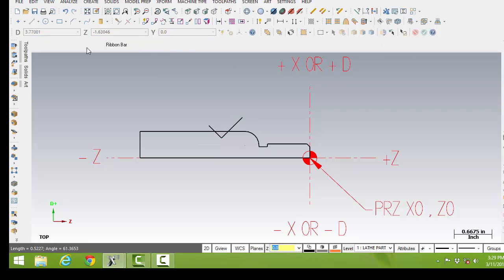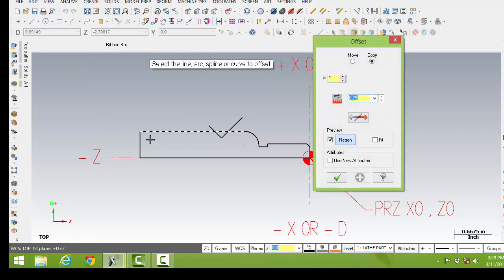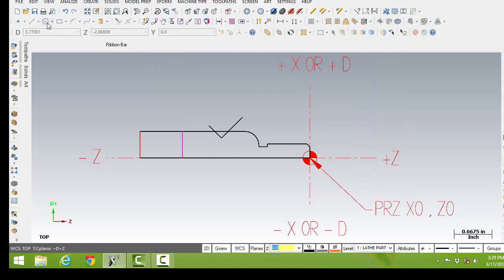The next one I'm going to do is do a circle. So I'll get a center point offset. What's offset? It's about 3/4 of an inch. We'll apply that. I'll create my circle and I'll come up here and I'm going to make a diameter of about 0.2 of an inch. I'll apply that and I can see that I have magenta, which is the result of the group I selected. You can also come up here and clear your colors anytime.